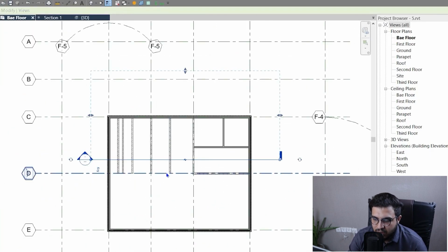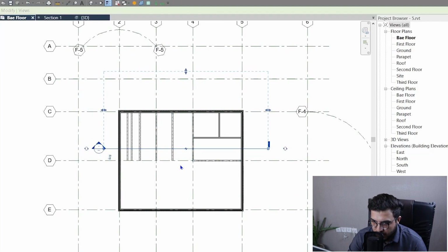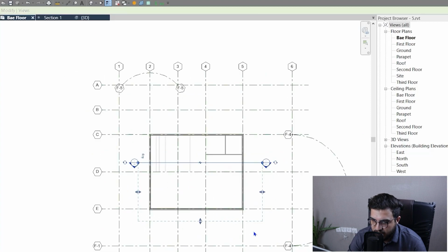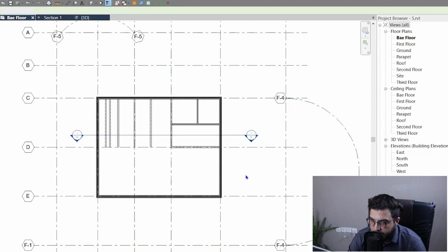And you can also create some split sections. I have uploaded another video about split sections; I will put the link in here. You can go and watch that too, and you can learn the split sections in Revit too. And you can change the direction of your section very easily with this tool you have in here. You can change the direction of your section very easily with this option.